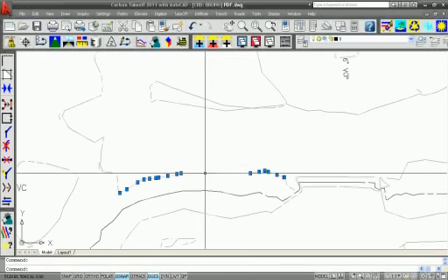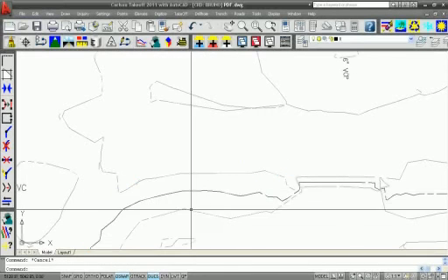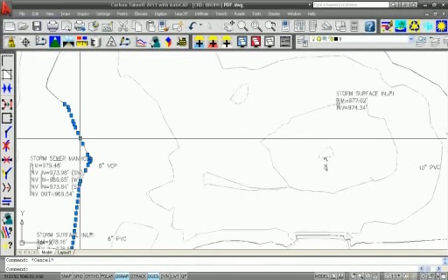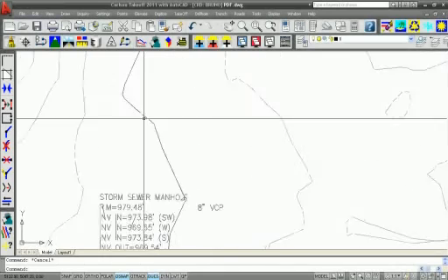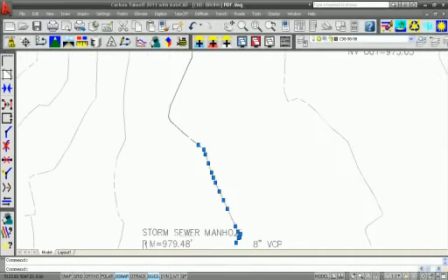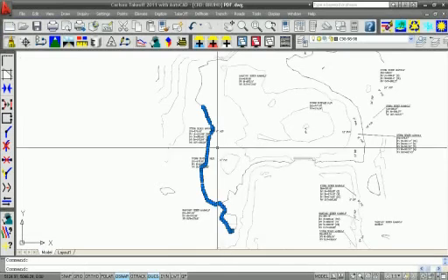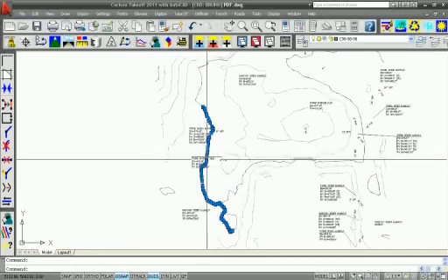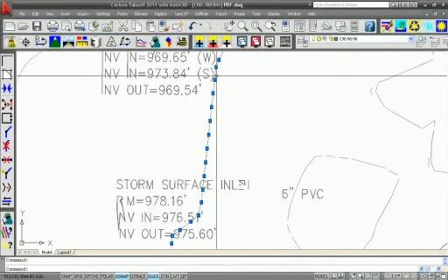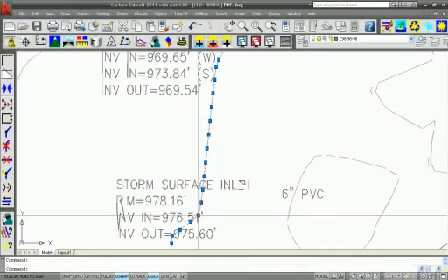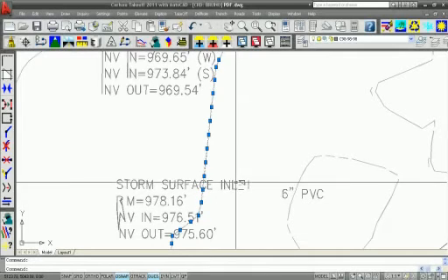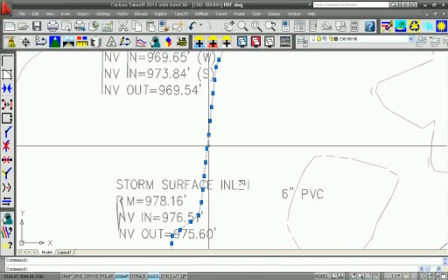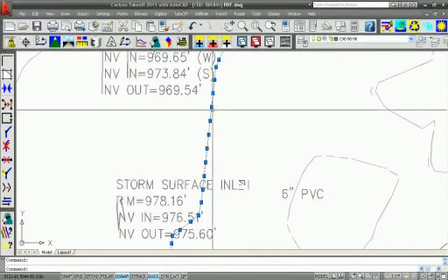And now I get solid lines on a lot of that line work. Okay. Now, are those grip panels considered vertices? Yep, those are vertices on the polyline. So we can now go into drawing cleanup and reduce this file even further, so that if we happen to be wanting to take this all the way out to a machine control situation, we have faster, better results. Right. Okay. Yep. So drawing cleanup would probably get rid of a lot of the points along this line segment here.